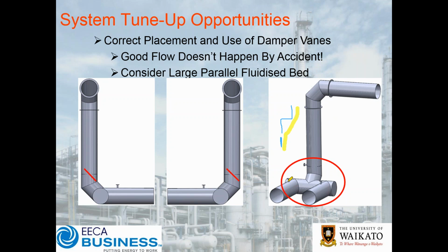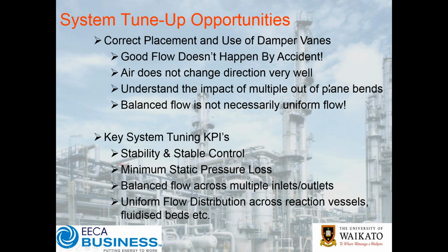And so these butterfly valves, even open at 100%, are going to disturb the flow and ruin the distribution of airflow across my system. In this case, it was a fluidized bed. So really, really important that we get this sort of thing right, and its attention to detail.